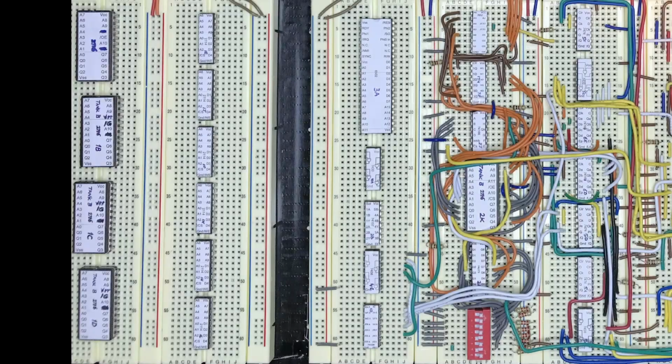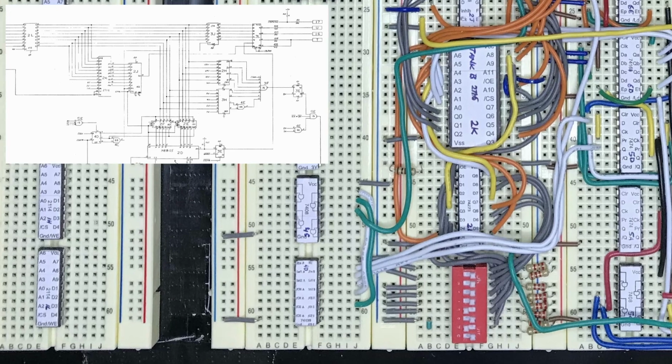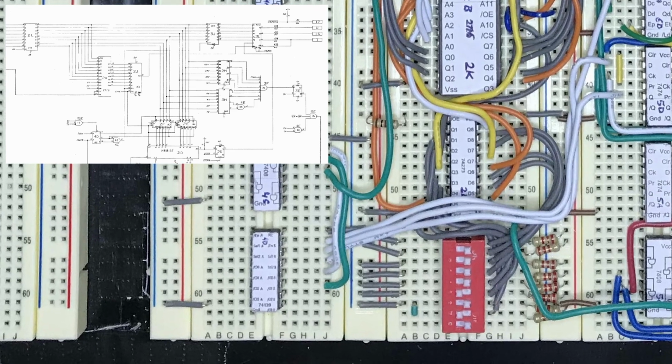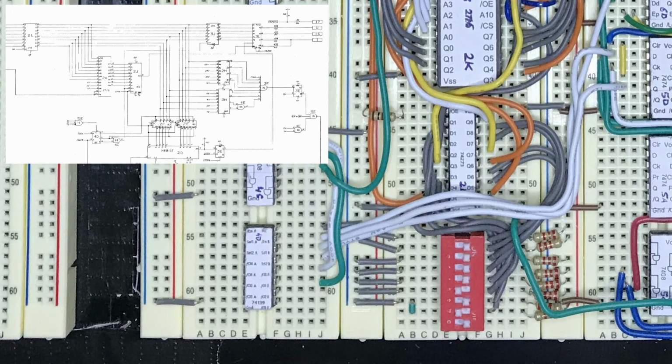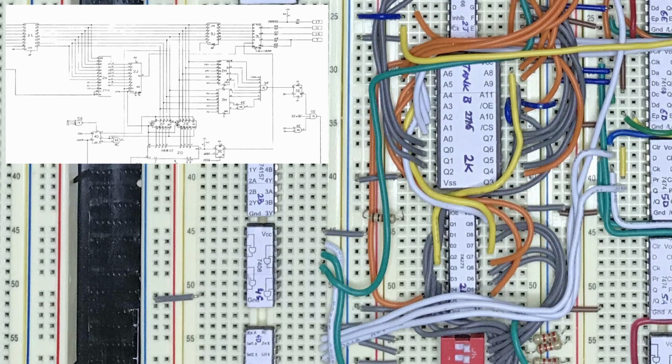So, here's the same circuit on the breadboard. In order to create a useful changeable data input device, I've included an 8-switch dip switch at the first part of the circuit. That red dip switch allows me to input any byte of data that I want, and so select a character to show on the screen. Next up, we have the 74LS273 chip as the input register to hold the data. It's not really needed here, since the dip switch is already holding the data pretty firm.